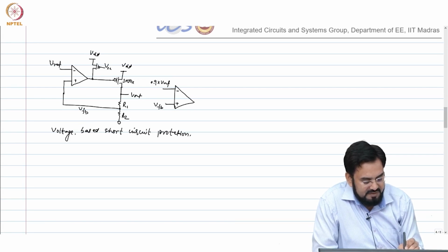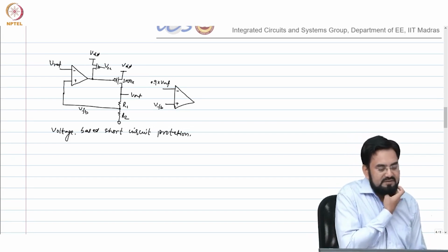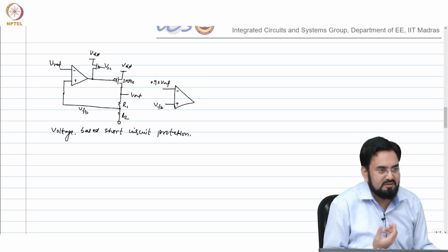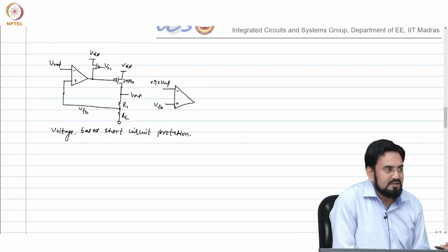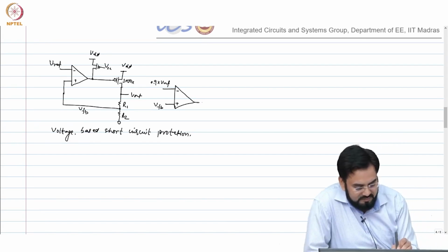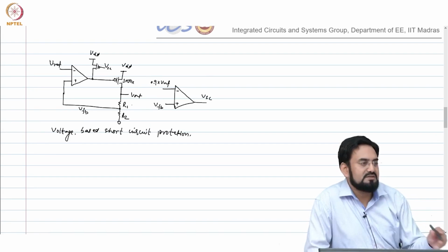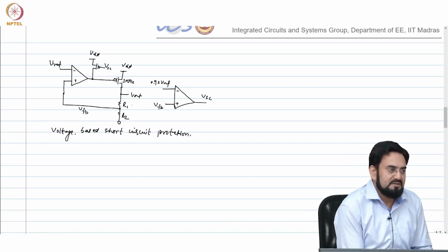So when VFB is higher than 90% of Vref, then you know it's in regulation. If you consider plus minus 10% of the supply, it will simply turn off when it goes below 90%.